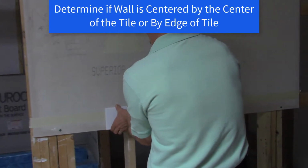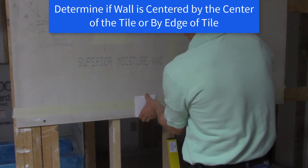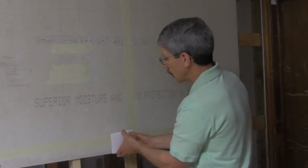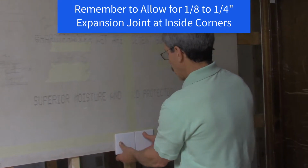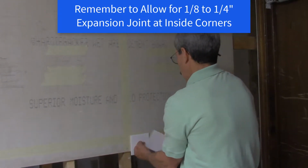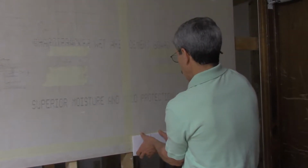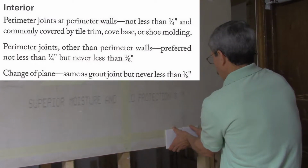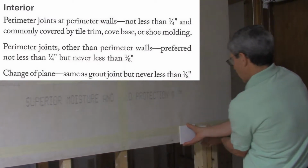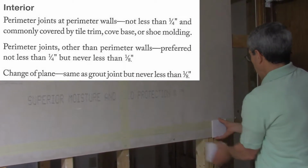You must determine if the wall will be centered by the center of tile or the edge of the tile to ensure the cuts on the sides shall be no smaller than a half tile. Remember to allow for an 1/8 inch to a 1/4 inch expansion joint at inside corner of walls. A 1/4 inch expansion is recommended. However, expansion shall never be smaller than an 1/8 of an inch, as shown in TCNA EJ 171 joint width.